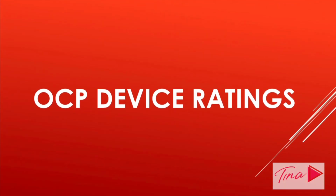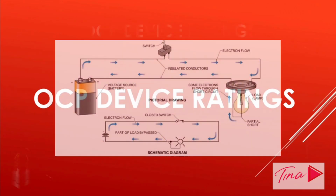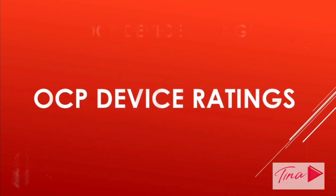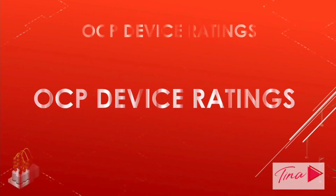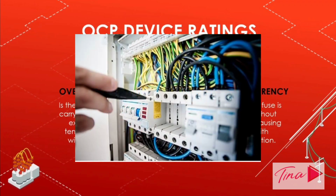Now we will proceed to the overcurrent protective device ratings. Now the OCPs have 2 current ratings, which are the ampere rating and the amperes interrupting current rating. Overcurrent rating is the highest current it can carry continuously without exceeding a specific temperature limit or without overheating.